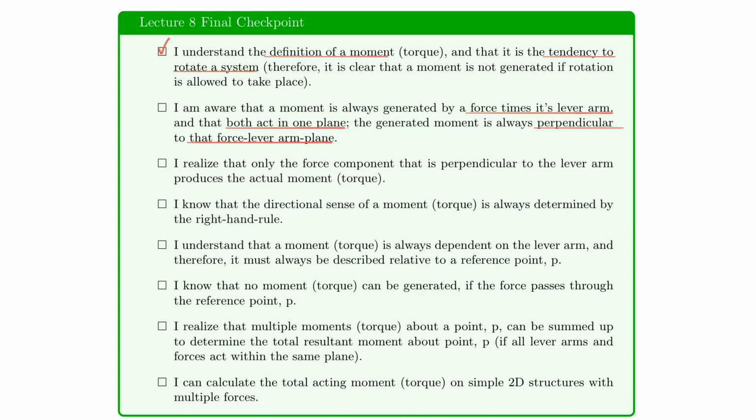And today you did not really have to worry about this. I mentioned this to you because we only dealt with XY planes, and therefore the moment was described by clockwise and counterclockwise, and therefore we got away with defining them as scalars and indicating the clockwise or counterclockwise. But in reality, those moments point in the z direction, and that's what we're talking about here, right? So you understand that the force lever arm plane is perpendicular to the actual resulting moment.